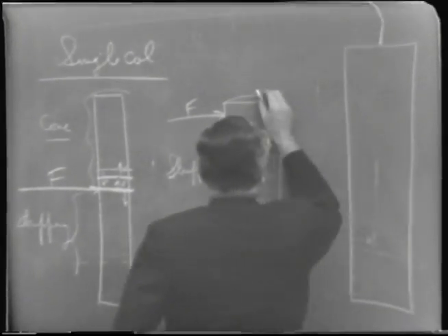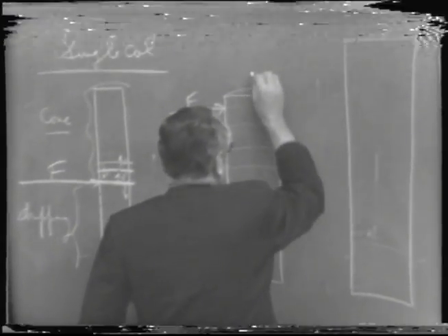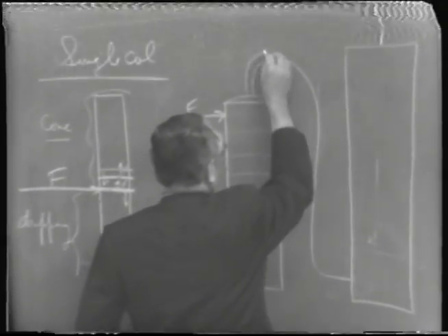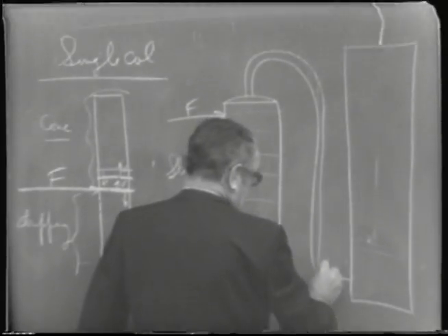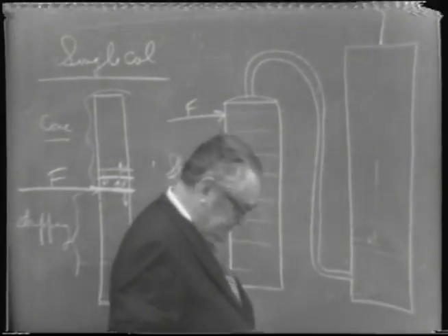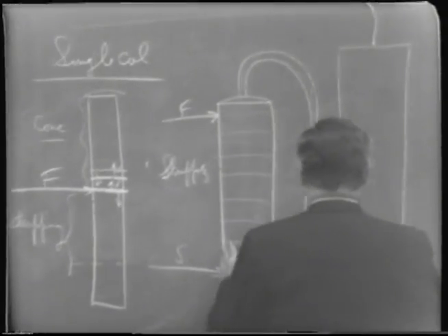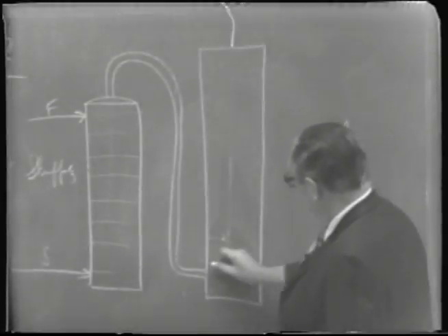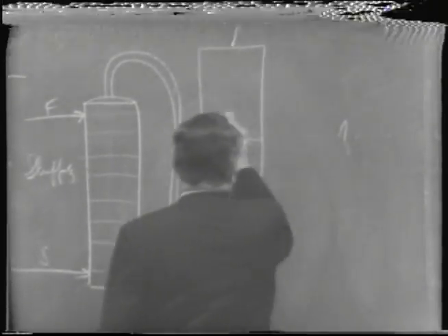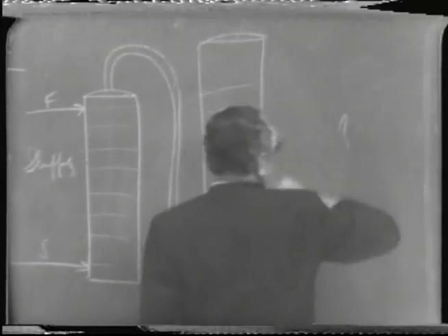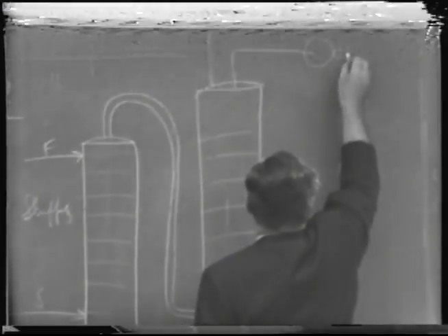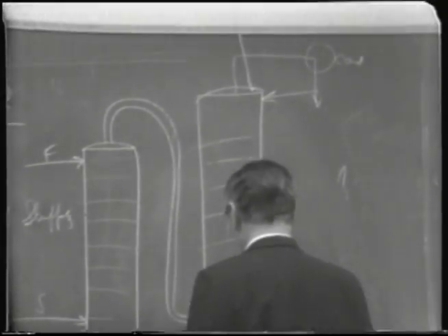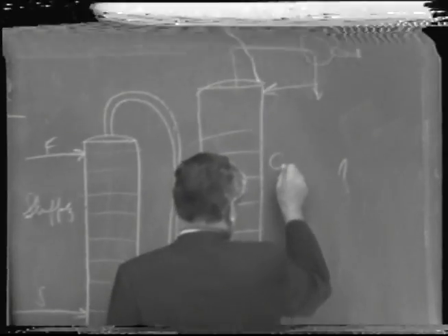in here, and now then, we don't have any condenser here, but we actually bring a vapor stream down to the bottom here. And so we have a big long vapor pipe. This in itself is a little bit of a disadvantage, but we are saving much in height here, you see. And so we have trays in here, and of course up here you'd have one or more condensers. And a certain amount run back as reflux in its simplest form. This would be the concentrating section.